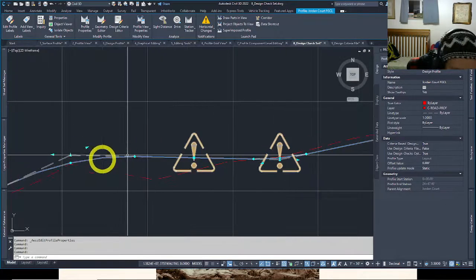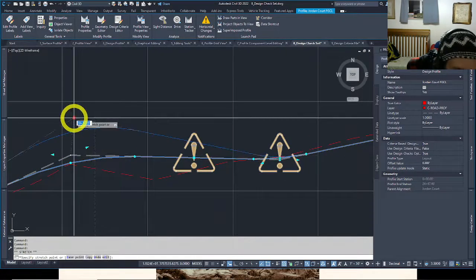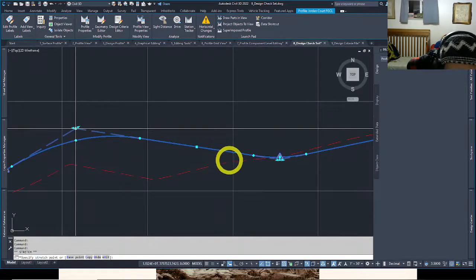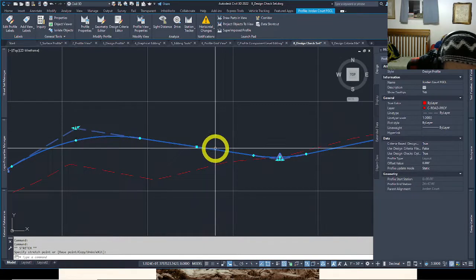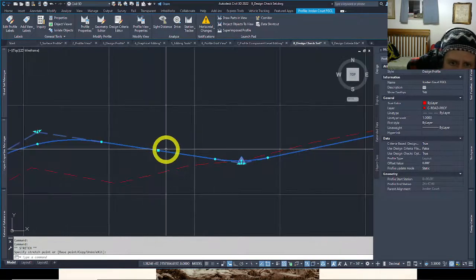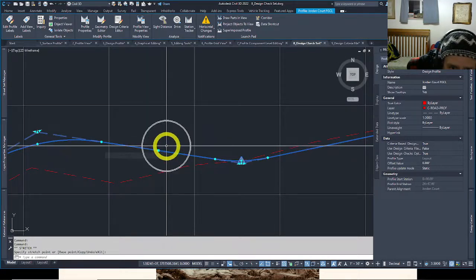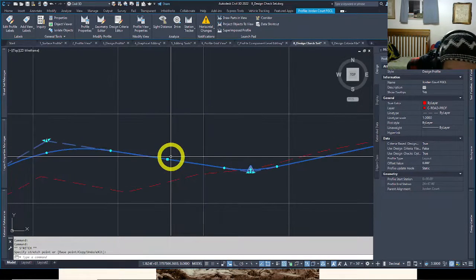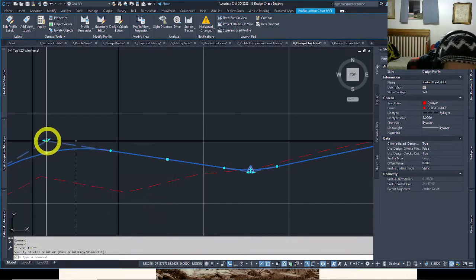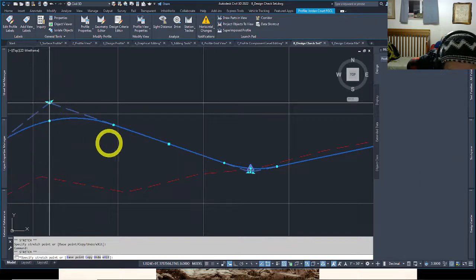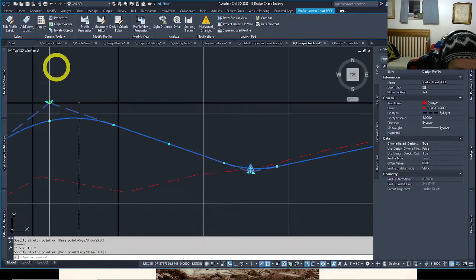Essentially, I'm just going to do a quick edit, sloppily or whatever. I'm going to move this PI up just to appease this warning, and it's gone because now I have a grade that is larger than, we're just doing the graphic. We're going to learn about labels more later. You would see a grade here that would change with it. You could actually see the grade graphically. It's not as steep as 0.5 or flat, or it's not as steep as 5. So if I went up this high, it's probably going to get too steep pretty soon.